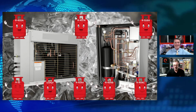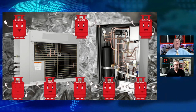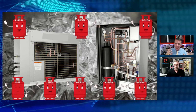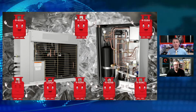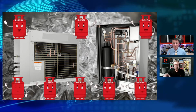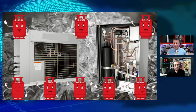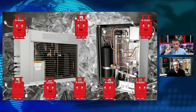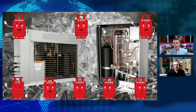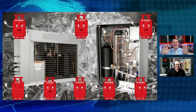Tom, thanks for joining in on us. We appreciate that. So that R32 is going to be an acceptable refrigerant. We may see R32 in residential light commercial air conditioning, as well as our split system commercial ice machines. It's also part of possible blends of some of those refrigerants seen on screen as well. It does have a low GWP of 676, so it's a good refrigerant. It is mildly flammable, and we'll dive into that.